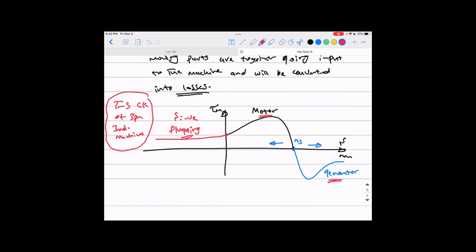Okay. So that's all I want to talk to you about for three-phase induction machines. We started like any other kind of machine. We studied the construction of the machine for the stator and for the rotor, for both the squirrel cage and wound rotor types. And we talked about the theory of operation, and how to generate a rotating magnetic field out of a stationary three-phase winding by applying three-phase voltage to them. And then we understood the theory of operation of such a machine, of how the torque is developed. And then we found how to model it using the equivalent circuit, the per phase equivalent circuit, and use it to predict the machine's performance.